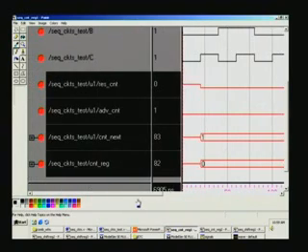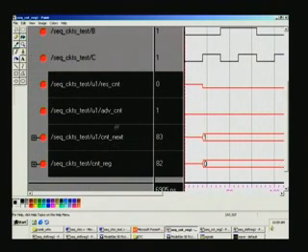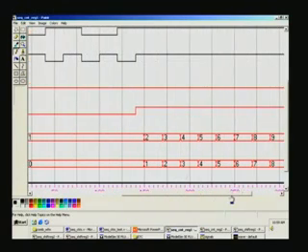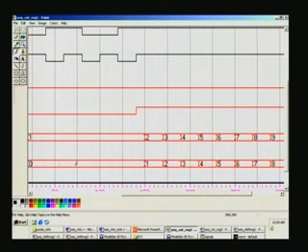And as mentioned before, we had an assign statement for counter register increment outside. So this will go in advance when compared to this. That's what you are seeing here. See, after when counter is 0, counter next is already 1. So in advance it computes. So you save time, thereby you speed up the operation. Frequency of operation is enhanced because of that. So it starts counting 0, 1, 2, 3 all in decimal here.